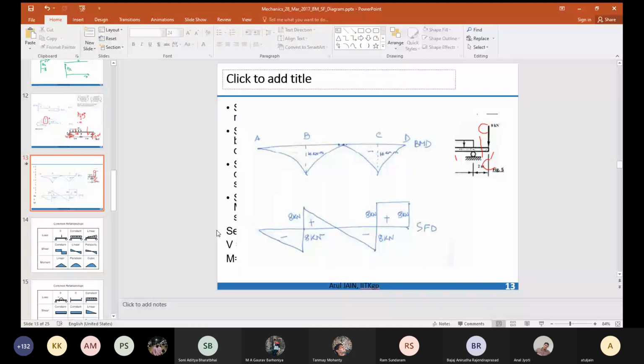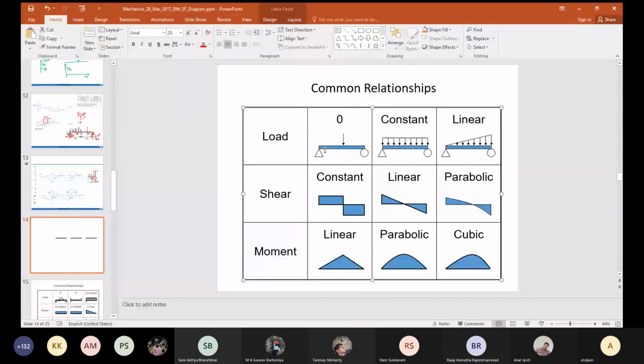Let's look at it. Let's say this structure. So this is a beam subjected to point load. Shear force is independent of the length. Moment increases linearly as the length increases. So if this structure is above a certain length, the only dominant load on this is bending moment. So those members which are predominantly only subjected to bending moment actually are called beams. That's why in the lecture that we have got, I think a statement was made. A beam is typically length is 5 times the radius.